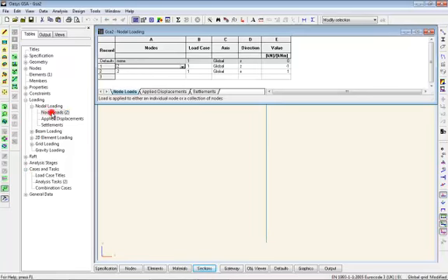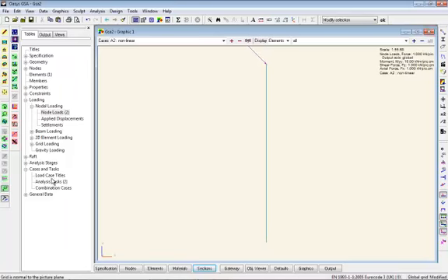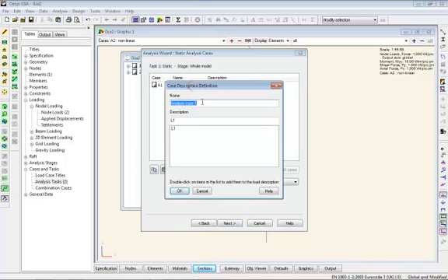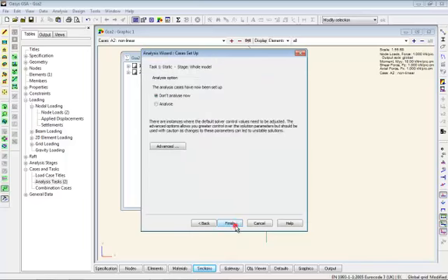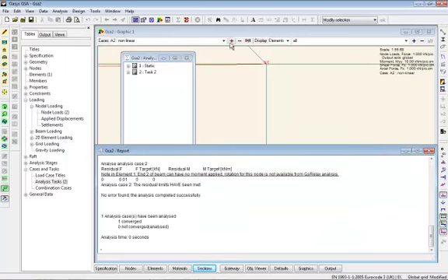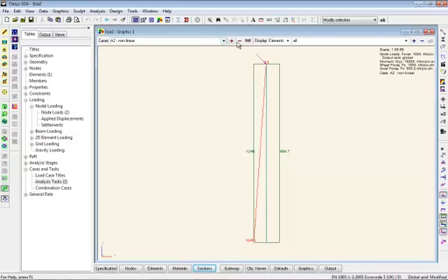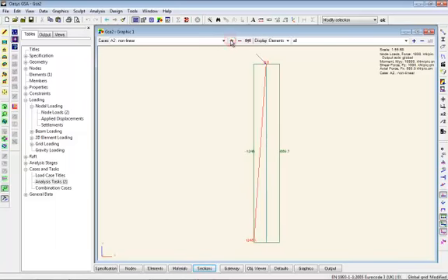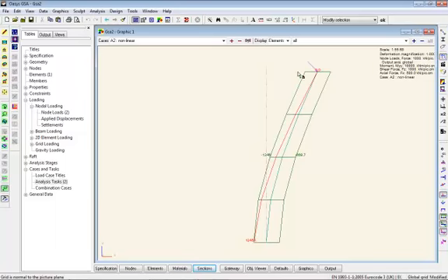Now if we boost these loads by, let's say, a factor of 1,000, we'll just rename this one so it's linear, be easier to read. Okay, we have results. So the linear is still giving factored results. The non-linear results now are looking quite different. And the reason for this is deflected shape. This is a one-to-one magnification on the deflection, so it's moving quite a long way from the original.